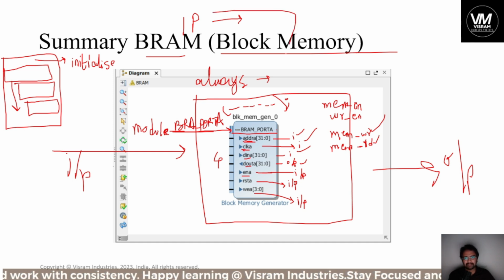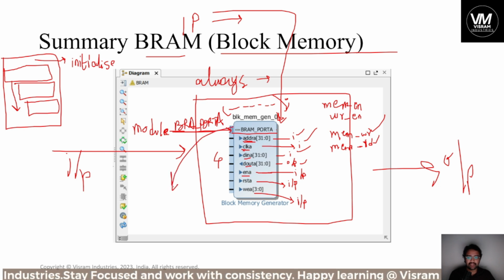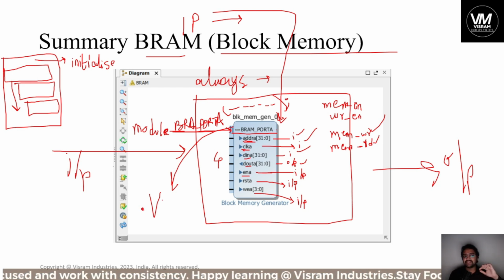So you can collect a direct piece of hardware like this and then generate it. Simple. Remember, from this IP Integrator we selected block RAM and generated a Verilog HDL wrapper .v file. We didn't write the Verilog HDL for it, but we took a Verilog HDL wrapper, and it has made some Verilog HDL functionality for us. Hence it has inputs and outputs like this.